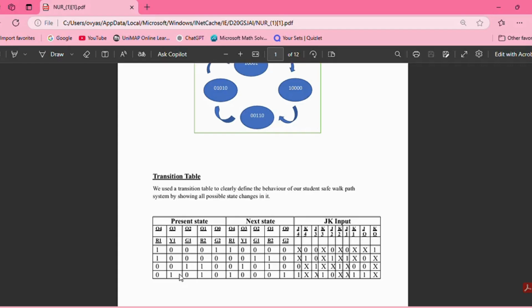The reason for having this second state of only red on high for vehicles is because before this we had a yellow light for students, but it seemed too complicated having 6 bits, because now we already have 5 bits. If we add another one, it will be more complex and harder to solve. That's why we only go with the 5 bits, and it caused us to have this one state where the red light for vehicles will be on high.